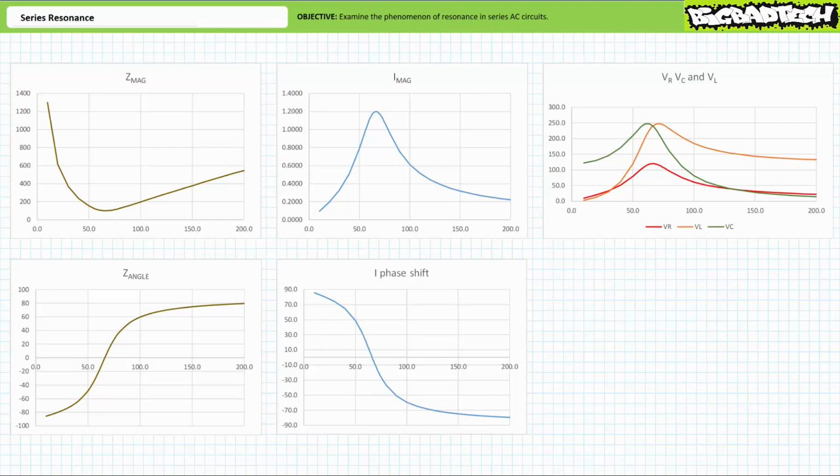Essentially, the opposite holds true for the inductor in orange. At low frequencies, the inductor drops very little voltage. As current increases, voltage across the inductor increases and peaks near, not necessarily at, the resonant condition. At increasing frequencies, the inductor drops the majority of supply voltage.